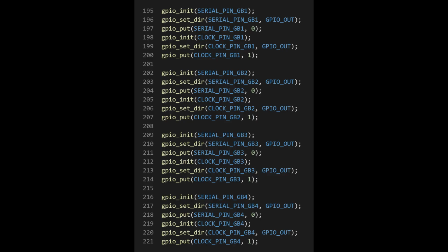At this point, I should probably mention again that the GameLink protocol, by its definition, is actually supposed to receive and transmit data at 5 volts. However, during the development of MahPicoBoi, I just happened to stumble upon the discovery that 3.3 volt digital signals work just as well and do not actually require a level shifter. But regardless of such electrical minutiae, we can now get into receiving, translating, and transmitting our signals.